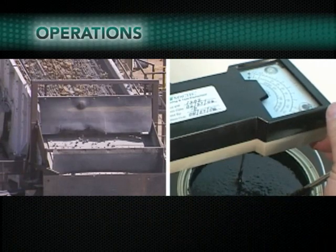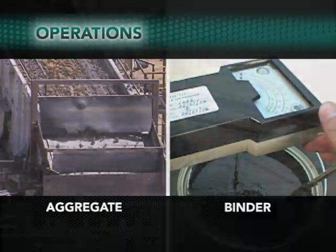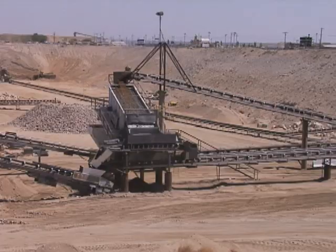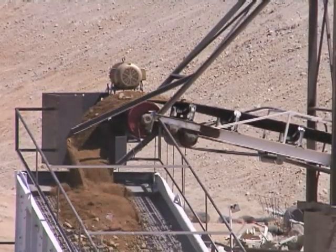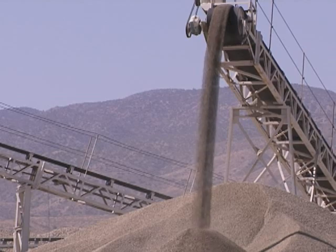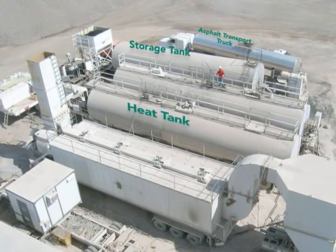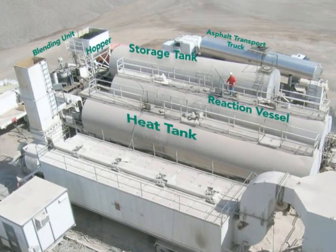Operations are split into two components: aggregate production and binder production. Aggregate production follows the normal manufacturing process for conventional hot mix asphalt. This is comprised of the mined or quarried aggregate being processed into the specified gradations as identified by the mix design. This is commonly referred to as the aggregate skeleton. Additional equipment is required on-site to produce the RAC asphalt rubber binder product.